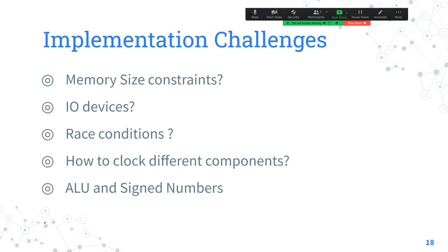So basically the chip has LUTs. I don't know the full form. There are 6,000 LUTs. When you write the Verilog code, whatever you use, the NAND gate, OR gate, MUX, registers, wires, those are all finally LUTs. When you say wire, there will be a kind of wiring in the LUTs. When you say register, they have a separate kind of LUTs. So LUTs are what get used up as you keep increasing your code. When you include even memory inside that, you have fewer LUTs, and you cannot use them for the processor and other things. So that's what we got.